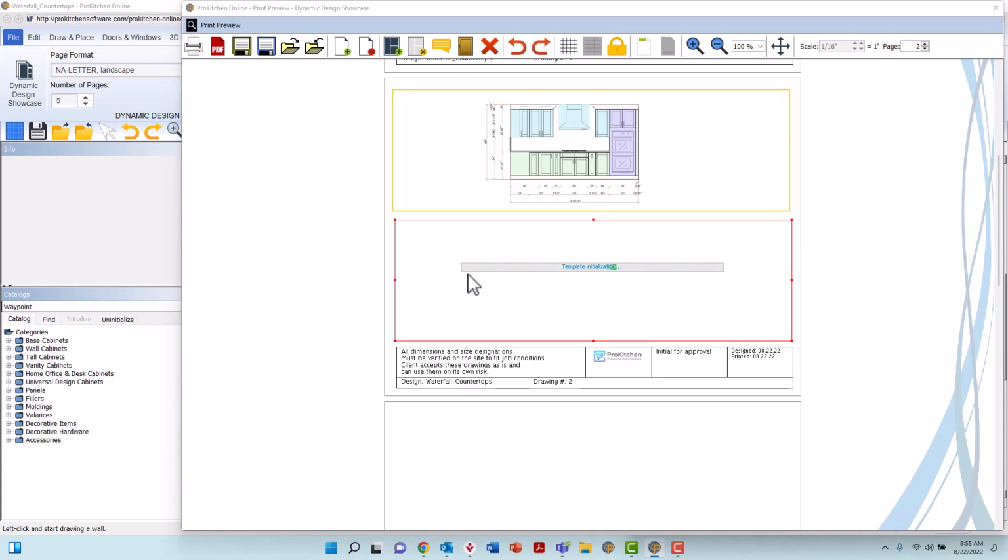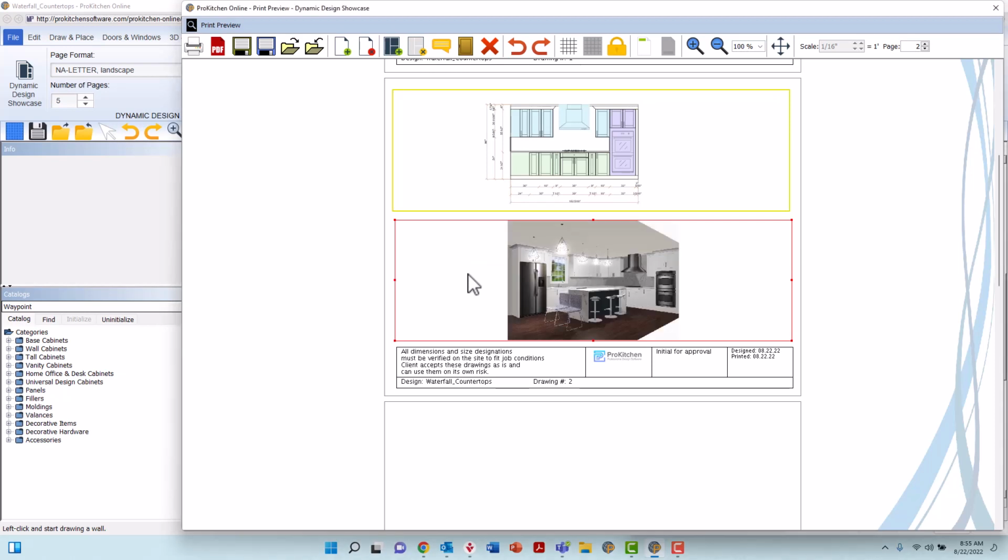What is happening here is that the template is remembering which view you want to go in this space every time you use the template, and it is internally opening the 3D viewer, rotating the design, turning Refine on if 3D HD was selected, and capturing an image to drop into your showcase. Once it has completed the task, the selected view will appear on the page.